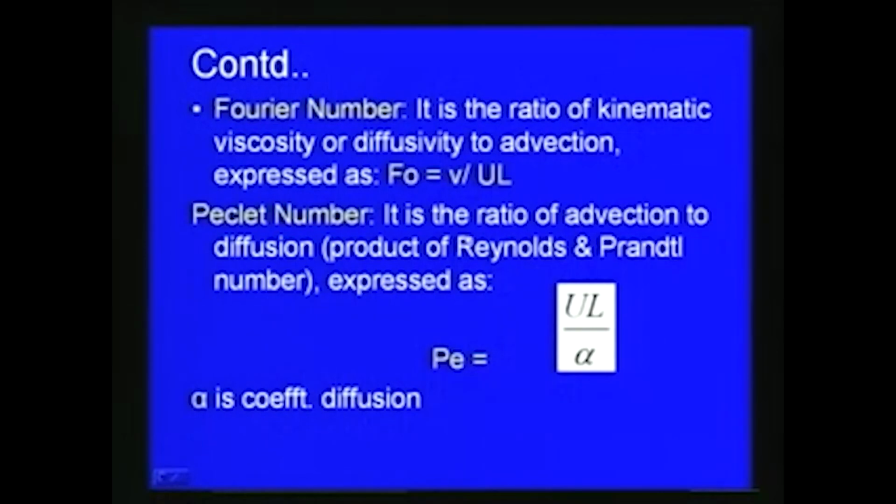So, with respect to this, when we do numerical modeling, we will be checking the Peclet number, so that we can see that the numerical modeling which we develop will be stable with respect to the various other parameters. So, this is called a Peclet number, and another important dimensionless number is called a Richardson number. Wherever the buoyancy effect is very important, this number is used.